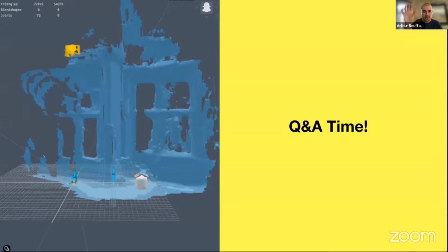You get a mesh as small as possible, but then for that building, you're going to want to walk away and do as many viewpoints as you can, and really max out the viewpoints, because that's the most important. Because if someone opens that experience and doesn't point it exactly at where you were scanning, then it's not going to work. So you do want a very small mesh, but a lot of viewpoints.